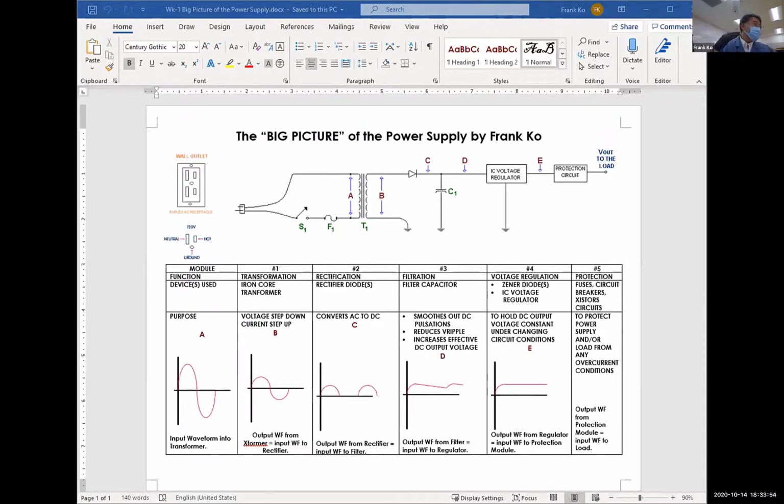If we removed the other half of the waveform, if we remove the positive half and retain the negative half, then we would have a waveform called negative pulsating DC. But in this case, because of how the diode is arranged, we have positive pulsating DC. So it has been changed. It has been converted. The waveform has been converted from AC now to DC.